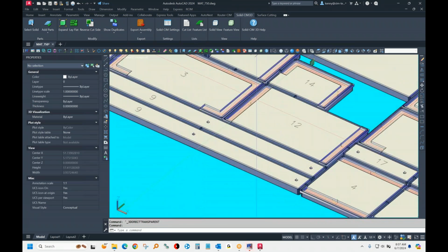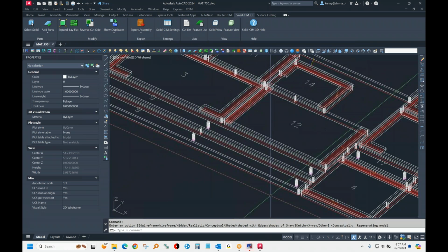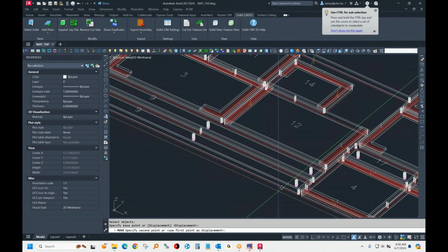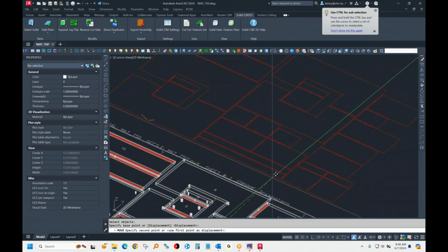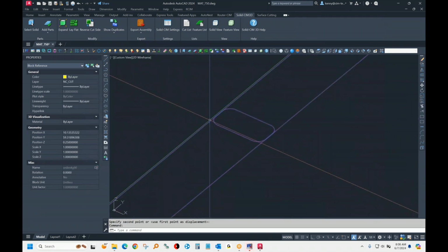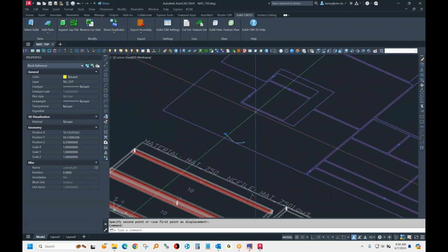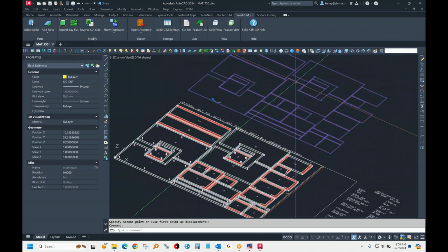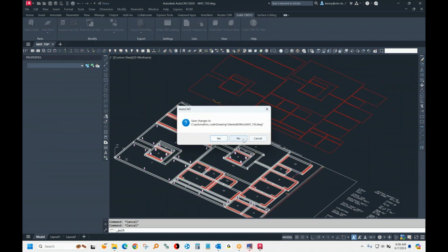And there's what's called a tool stay down nest on here. So the tool stays down and cuts part to part without lifting up. That reduces your overall cycle times. There's 1 lead in and 1 lead out. And the tool has a little overlapping bridge. So the tool comes off of this part on an arc, goes into the next part on an arc, cuts that out, comes off on an arc, goes into the next part on an arc. It's very fast and smooth, keeping the tool down and connecting part to part without lifting up. Reduces the overall cycle time.